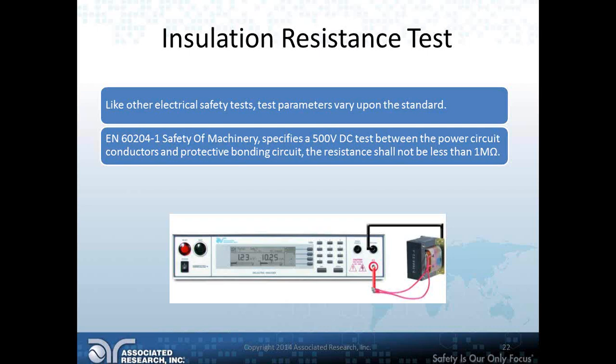Okay, so now that we've covered most of our electrical safety tests, the last one that we did not touch on is the line leakage test. The line leakage test is very different from the rest of the electrical safety tests that we just talked about. It is performed on electrical products to measure the leakage current which would flow through a person while the product is operating. So here is the key, the big difference between the line leakage test and all the other safety tests: this test is performed while the product is actually powered on or running.